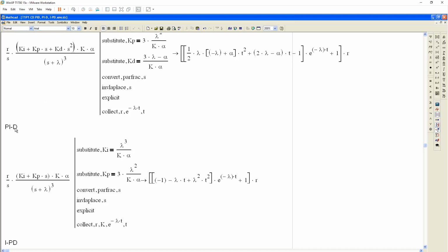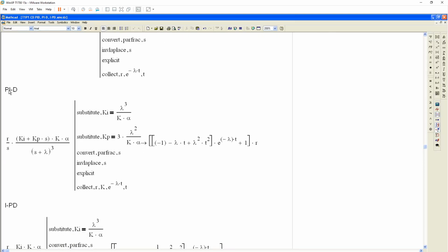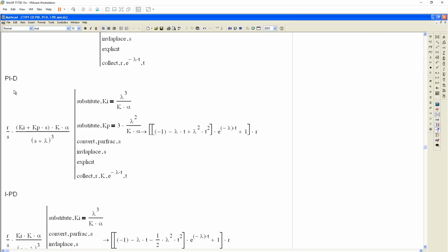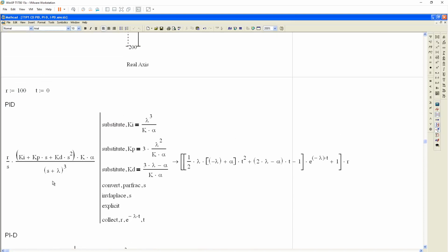In this case, this is a case you see in many PID controllers on PLCs, and the PI is working on the error between the target and the actual, or the set point and the process variable, and the D is only acting on the rate of change in the process variable, or in my case, the error in velocity, which is the rate of change in position. Now, the difference between them in the Laplace transform is that I don't have this D term in the numerator. So that means that there would be a D term only in the feedback path.